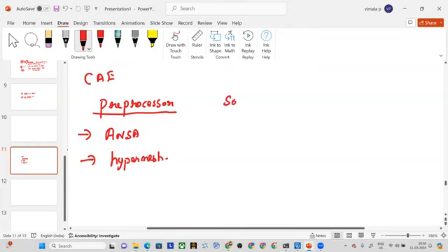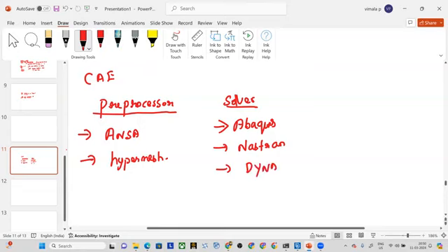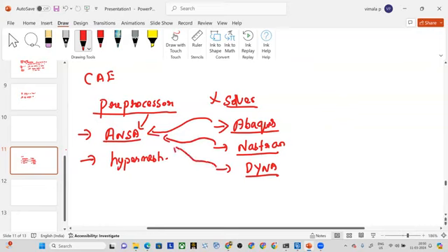Then for solving, I said, what type of calculator you are going to choose? For solving, you have got n number of solvers, out of which the popular ones are Abaqus, Nastran, LS-DYNA. ANSA itself is a preprocessor. It does not contain any solver. These are separate software, but ANSA includes all these solver modules in it, so that you can solve using these calculators.